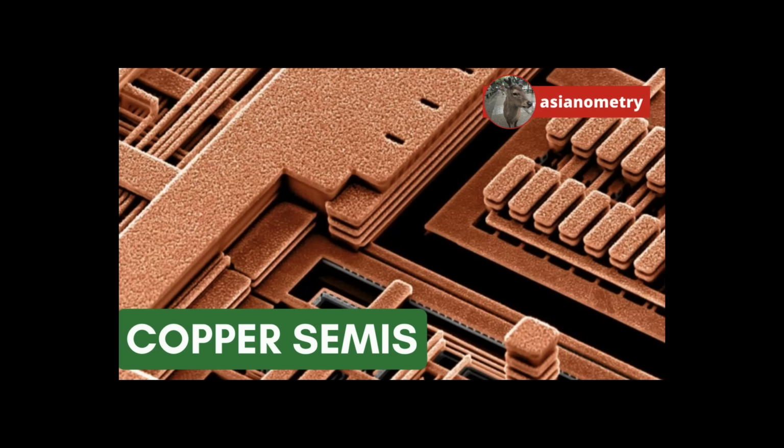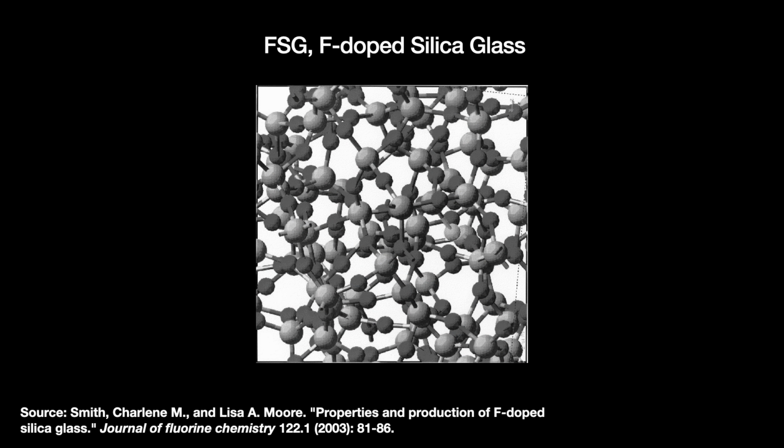I covered the dramatic story of the low-K dielectric race in a prior video, one of my personal favorites. A common early choice for the dielectric is fluorine-doped silicon glass, or FSG, essentially silicon dioxide doped with fluorine atoms. The later technology generations used carbon-doped oxide or porous silicon oxycarbide. Yes, it literally has pores.